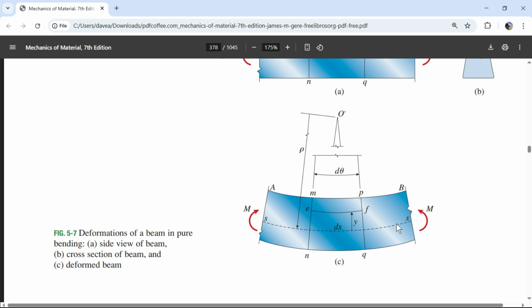And especially when we're trying to find the stresses, above this line we have crunching in of the beam. That's going to be compression with a negative stress. Negative numbers for the psi, the pressures that are attributed to that, the stresses. Stresses are the pressures. And then if I throw in a value of negative y, we have tension, and so everything's going to be getting ripped apart. Those are going to be positive values of pressure.